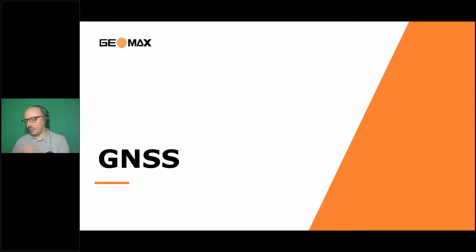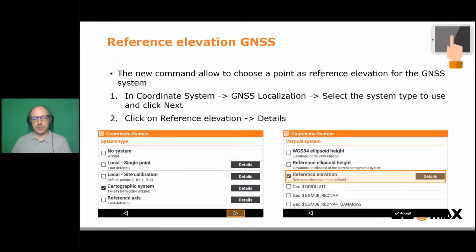GNSS. Okay, now let's see a very interesting function for the GPS. This new function allows you to define a local elevation system. What does it mean? Until now, when you were working with the vertical system, so with the elevation of the GPS, you had in the end few possibilities. You can work with the ellipsoidal elevation, you can work with the geoid, so with the elevation over the sea level. If you have a local system, a site calibration, for example, you can also select a local elevation, but it will be the elevation of your local system.